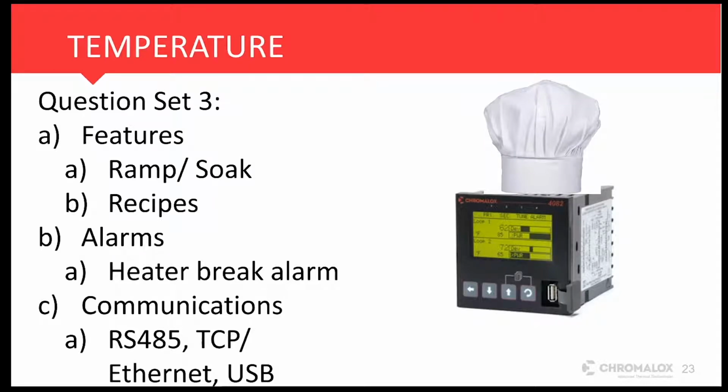And then finally, we have communication options. A lot of the times for simple applications, you're not going to need to worry about that. But if you do start to run into some requirements with Modbus, RS-485, TCP, Ethernet, things of that nature, just take a look at that chart that I keep going back to, and make sure that it's on there. It really is as simple as that.